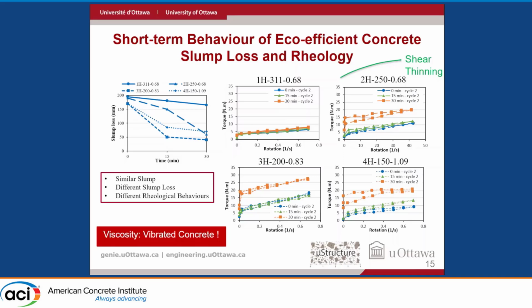This one, actually, has a decrease in viscosity as a function of the torque applied, meaning that it would be a very good concrete to be vibrated, even with a very low amount of cement and very high amount of fillers.